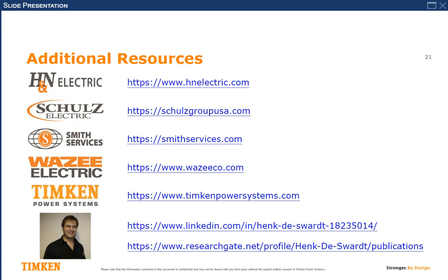The other thing is that you can try to use ultrasonic testing for things like partial discharge. But again, partial discharge I can very easily measure from the outside, so I've not seen people use that in general. Occasionally I've seen it here and there, but not a lot. I don't know if the technology is widely enough accepted. It is available for sure, but I don't think it's been established well enough. There's other testing that you can do much more easily, which has been established in the market and used for many years. So maybe the customer has something specific in mind, and we can discuss it afterwards.